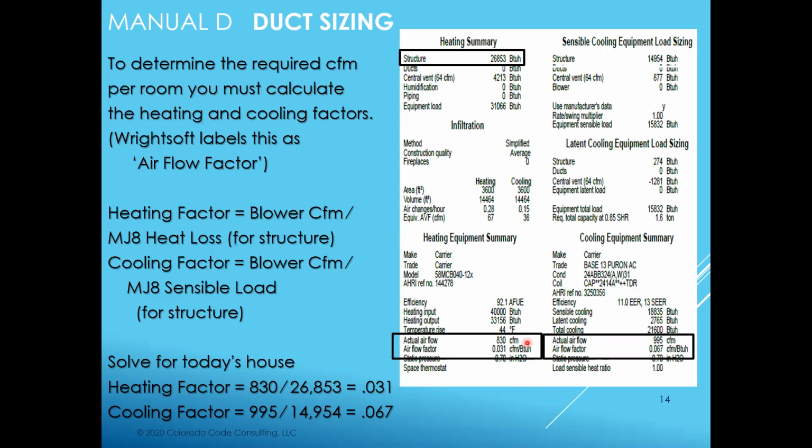So if my original plan said I needed 50 CFM to a room, as an example, but all of a sudden I take that 830 and I jump it to 1200, as an example, what's going to change? The room-to-room CFM will certainly change. Absolutely, positively. Usually it's not that extreme. I guess what I'm saying is for your jurisdictions that are doing room-to-room flows at final, and you're finding that they're off, it could be as simple as going back and changing that CFM number right there, and then boom, software does the rest.